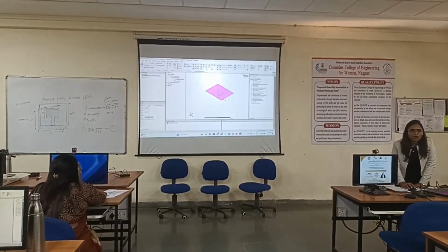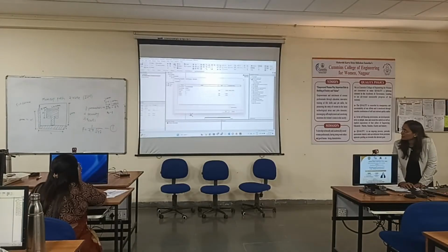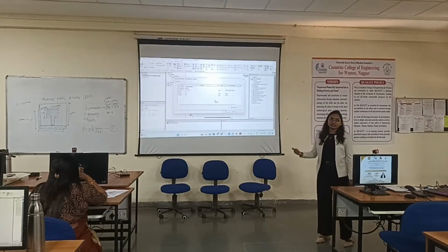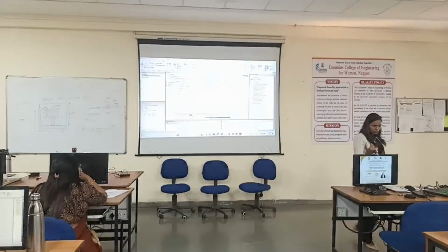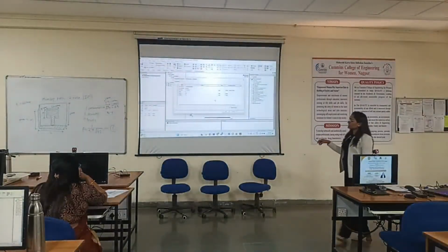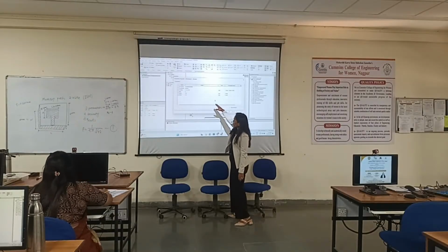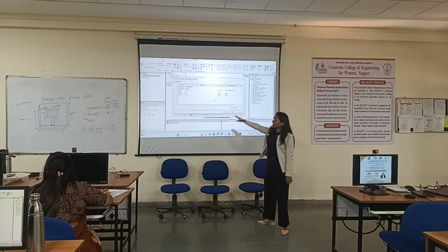I hope you all have this rectangle one. Just double click on create rectangle. You'll get this pop-up window. Here we have to assign the positions. So positions would be -30. Here you can see now it is -1.2, -1.02 and 0. So you have to type there.